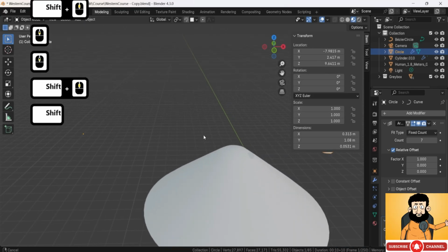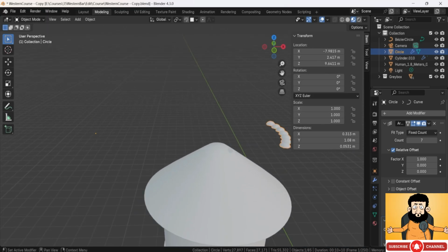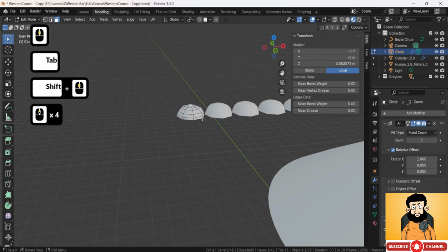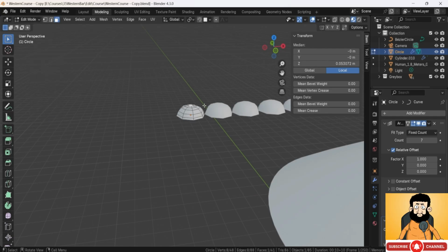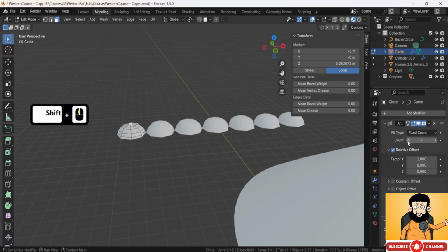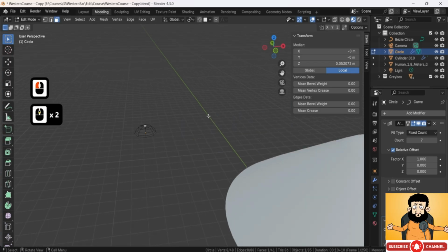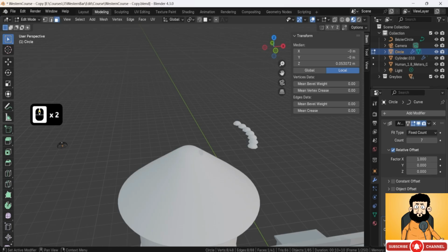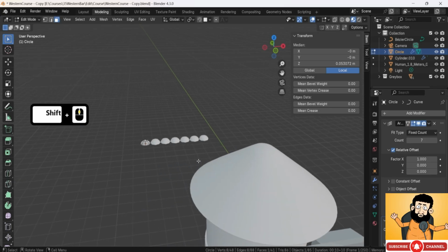And if you're wondering, by the way, how I disabled this curve, we can use these icons over here. These icons are very nice whenever we want to disable or enable them, whether it's render view, viewport, or even edit mode. For example, right now this button is turned off, but if I go to edit mode, you'll see that it goes back. The reason being is that in edit mode, it just goes to a different view essentially, and the array itself will not have that ticked off, but the curve will have it ticked off, and that's why we're not able to see it. We can turn this on, for example, if we want to and see them back on, but again, it's probably for the best to keep this as is.